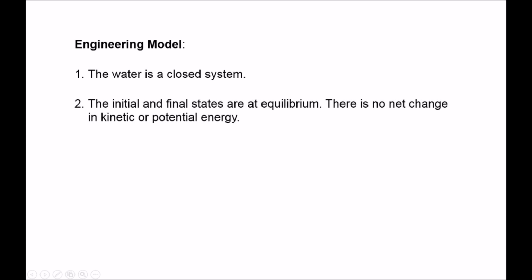The next step is to develop an engineering model, which is a set of simplifying assumptions which will allow us to perform the analysis of the problem. 1. The water is a closed system. 2. The initial and final states are at equilibrium. There is no net change in kinetic or potential energy. 3. There is no heat transfer with the surroundings as the tank is well insulated.